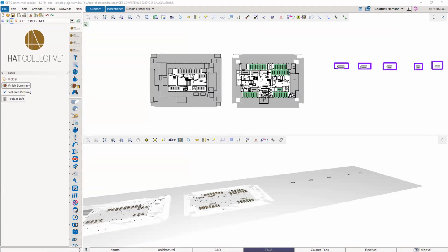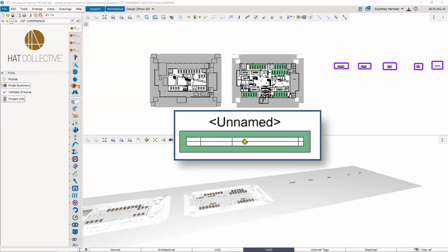Every manufacturer, or most, have a pick list, and you can find that in their first tab or at the top of their library. Doing that will allow you to drag this box into your 2D space. Once placed in your drawing, our friendly green box appears in the top left. Double-clicking on the pick list brings up this new screen.